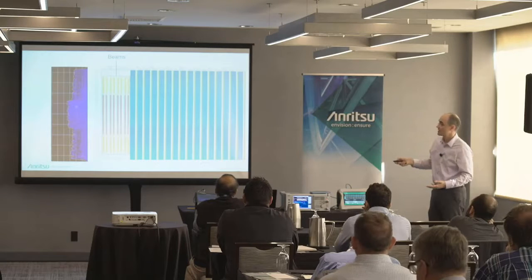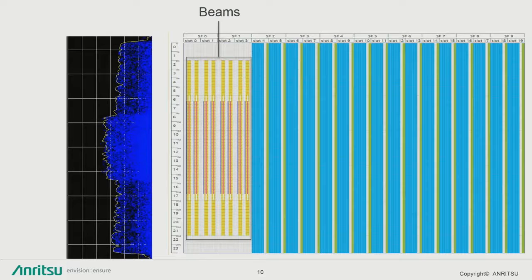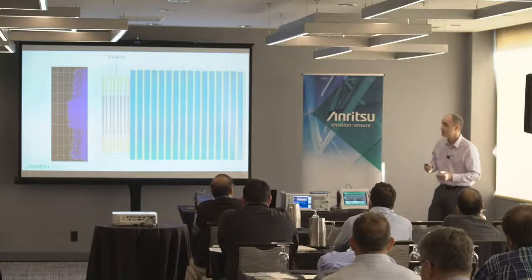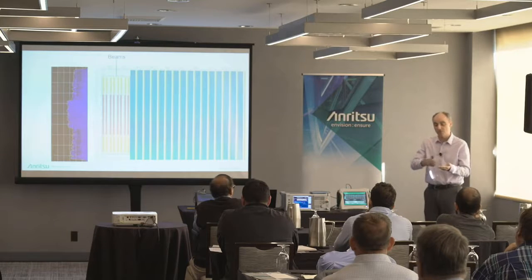Okay? On a spectrum analyzer, you'll notice that you've got a lot more density here, simply because this is always there every 10 to 20 milliseconds. Okay? Because it's always there, how many of you guys have used a real-time spectrum analyzer? Okay, so how many of you used a swept spectrum analyzer? Okay, so a swept spectrum analyzer will sweep through a particular frequency range, and when it sees energy, it'll plot it onto the screen. That's the simplest way to put it. And there's a local oscillator and some other stuff.